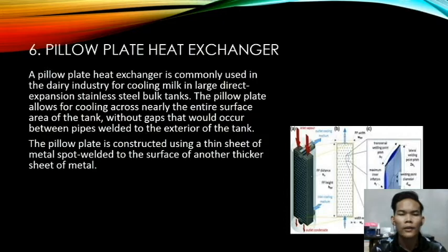Pillow plate heat exchanger. A pillow plate heat exchanger is commonly used in the dairy industry for cooling milk in large direct expansion stainless steel bulk tanks. The pillow plate allows for cooling across nearly the entire surface area of the tank, without gaps. The pillow plate is constructed using a thin sheet of metal spot welded to the surface of another thicker sheet of metal.